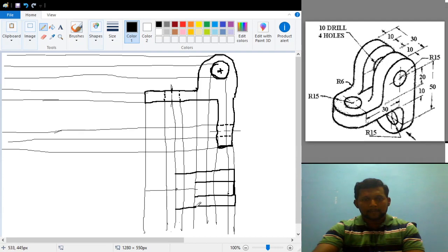Okay, and after this the semicircular arc. So this semicircular arc is nothing but this particular one, which is over here. And in the top view, we can clearly see the circular hole here. These circular hole dimensions, we have our projection lines taken from the front view. So from here you can neatly draw, with 5 mm radius, a 10 mm diameter circle.